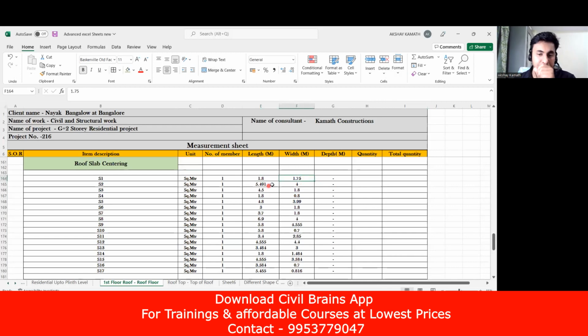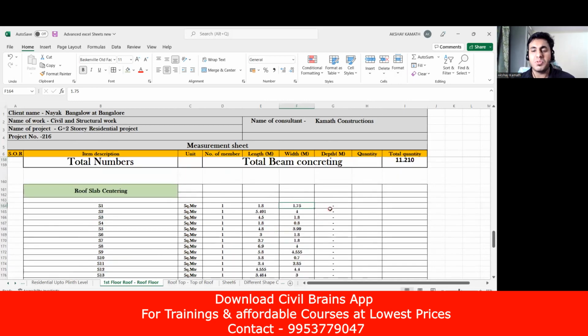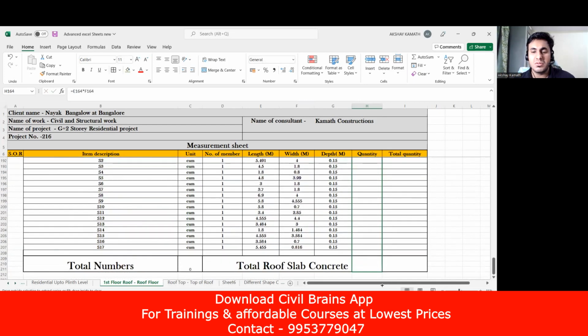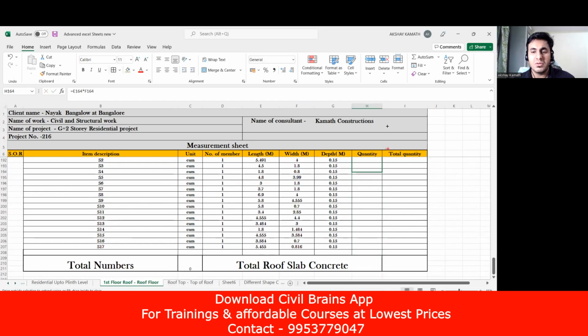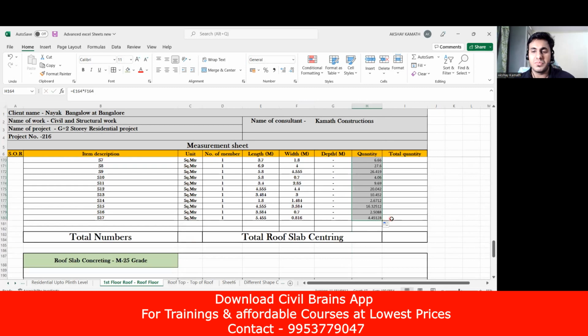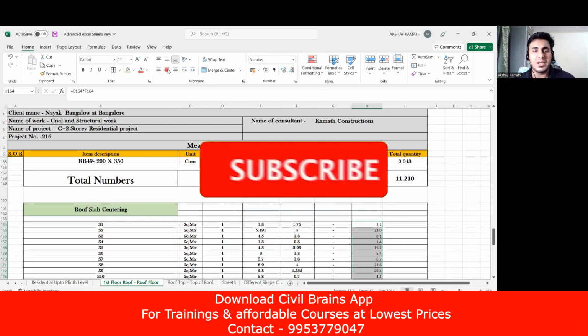In this way, for all the slabs I've calculated. Okay. You also do the same thing. Depth we don't require. I'll do the centering quantity. I want area. So 1.8, I'll multiply this by 1.75. Done. I got the centering quantity. I'll drag it here. Okay. I'll drag it up to here. What happened? Yeah, it should be up to here. Done. So I got all the centering quantity. I'll take it to the center.